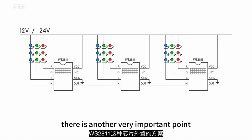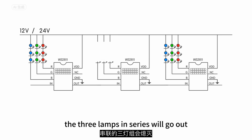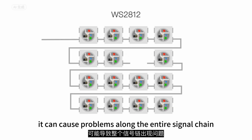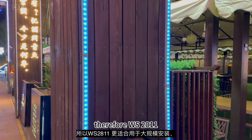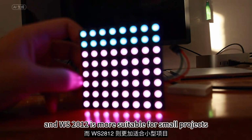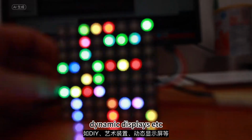There is another very important point. With WS2811, this chip external solution, even if a certain LED malfunctions, the 3 lamps in series will go out, but it does not affect the normal operation of other parts of the entire light strip. And with WS2812, once an LED is damaged, it can cause problems along the entire signal chain. All subsequent lamp beads fail. Therefore, WS2811 is more suitable for large-scale installation and long-distance power supply reliability scenarios. And WS2812 is more suitable for small projects, such as DIY art installations, dynamic displays, etc.